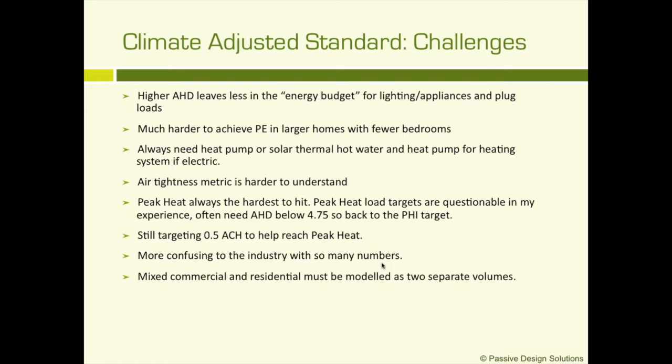Because people can wrap their head around air changes per hour, but CFM per square foot building envelope is more difficult to get your hands around. The peak heat load has actually been the hardest for us to hit, and I'll say from our experience that I'm still really questioning those targets set by PHIUS.